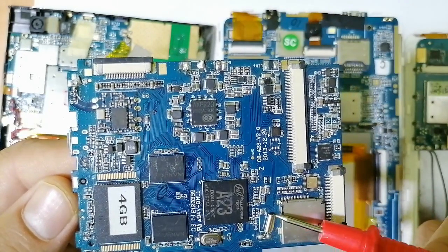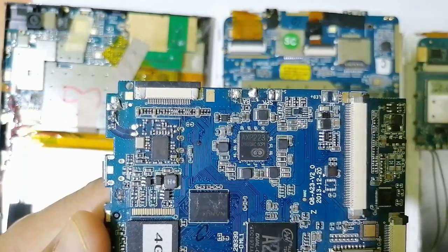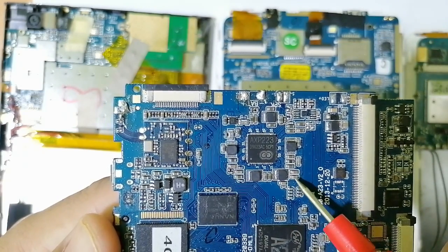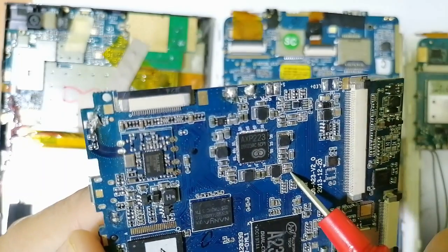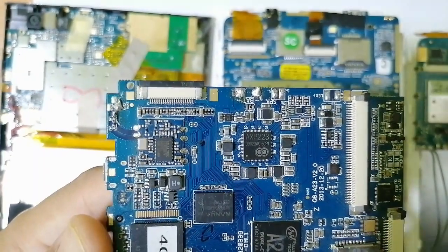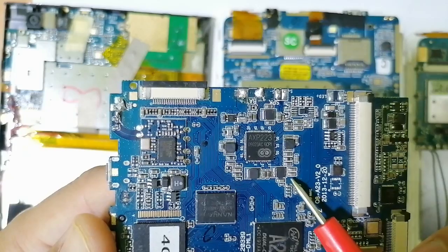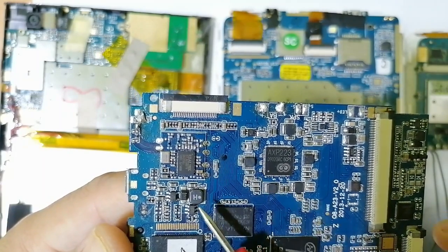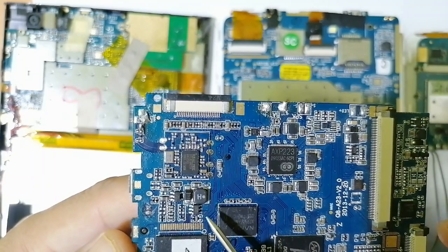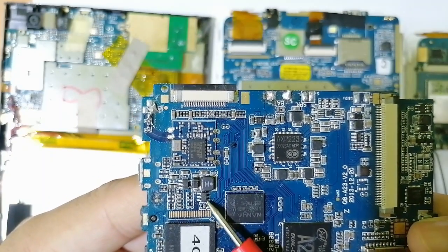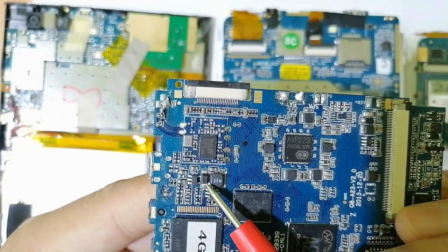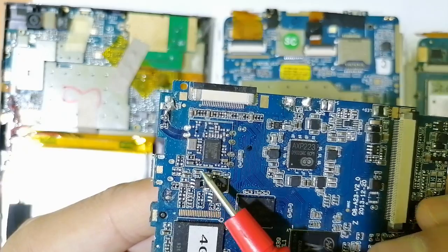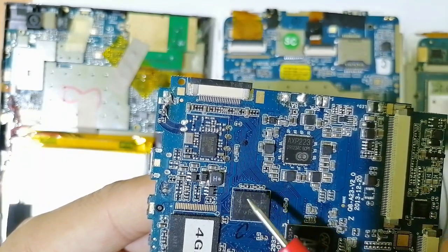This is basically the crystal oscillator. The components around the IC are ceramic capacitors. This is a very important component that I'm going to teach you how to test. Those are inductors. This also is an inductor. We have an IC over here, a voltage regulator. Over here we have a diode. This is a fuse resistor. We have 0 over here. I'm going to teach you how to test all these components.